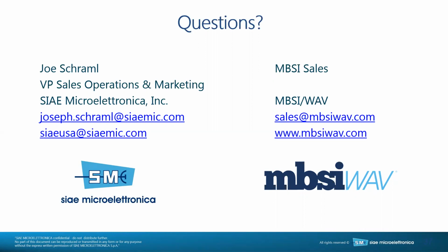The PoEs that we provide for those radios are rated at 95 to 100 watts, and we do that on purpose because we want to make sure that we also have the ability to have the PoE handle the inrush current when you first turn the radio on. So we typically oversize the PoEs about 20 to 25% just to make sure that those PoEs work with the radio. They work at the lower input voltage, as well as handle the inrush current. And that's one of the reasons why our radios don't have to back off the transmit power when we use PoE.